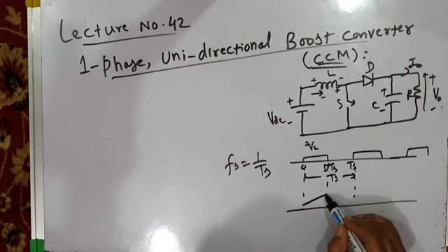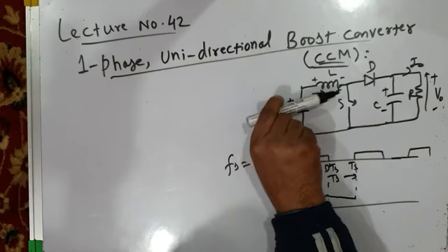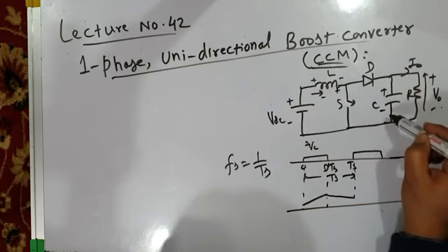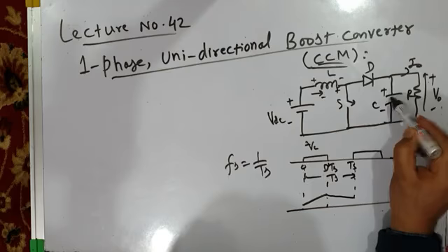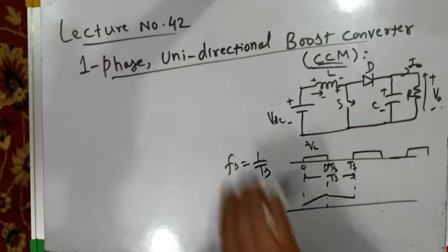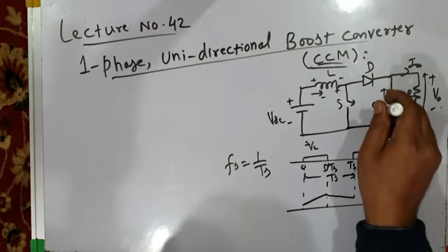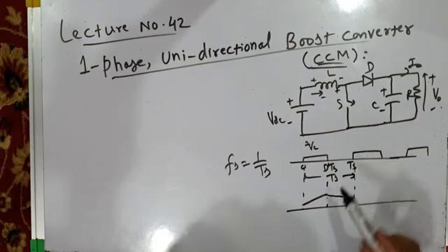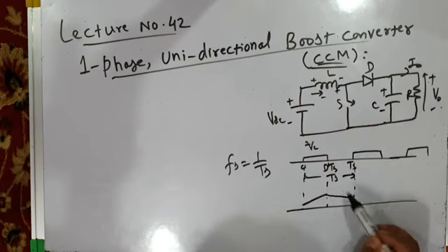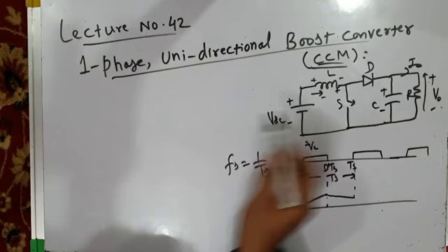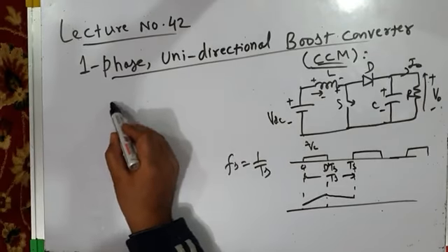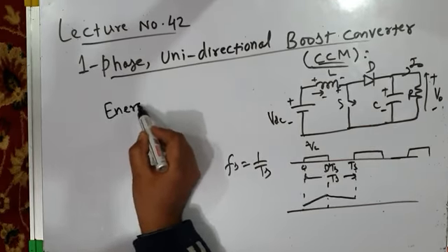And when the inductor is releasing the energy, we already know the current through the inductor decreases, because the inductor has to force current against a higher voltage. Since this is a boost converter, the output voltage is greater than the input voltage, and when the inductor has to force current against a higher voltage, which is across the capacitor, the current decreases. So there are two time intervals.